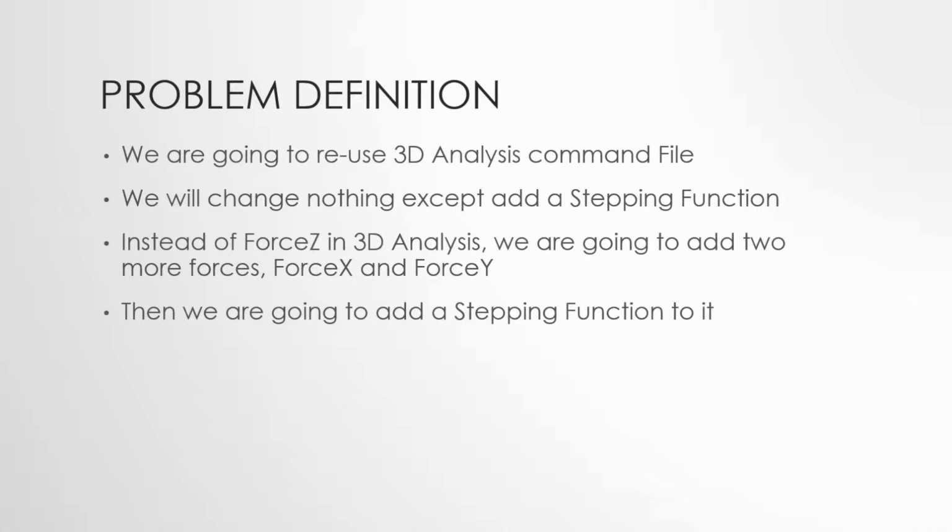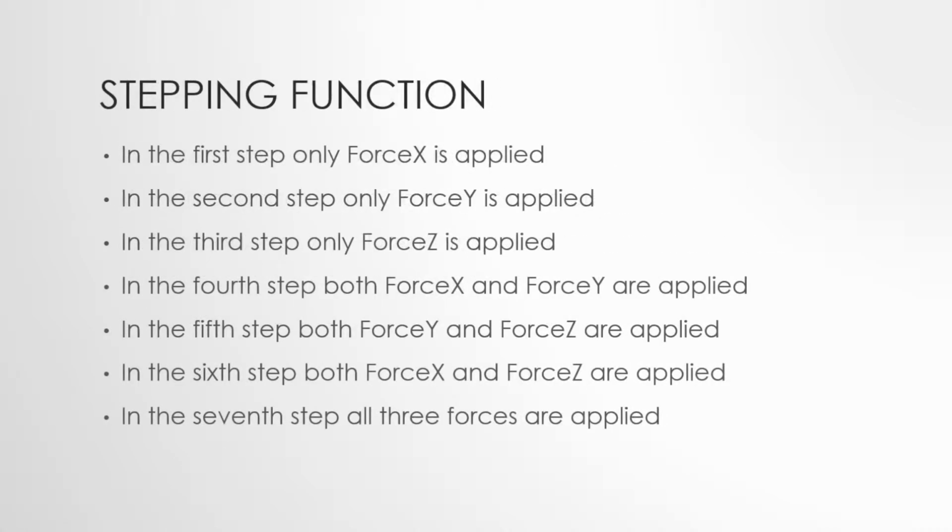Instead of force Z, which we used in 3D analysis, we are going to add two more forces, force X and force Y, both with the magnitude of 2000 newtons. Then we are going to add a stepping function to it. The stepping function will be applied as follows.